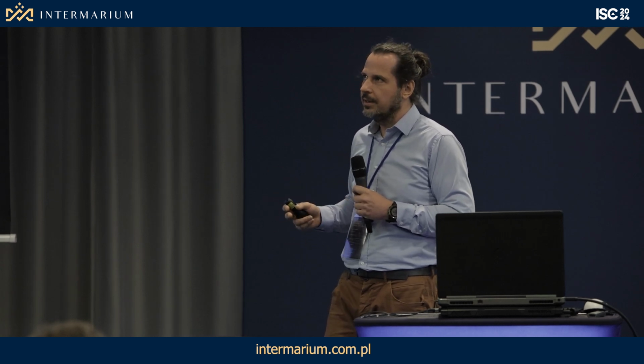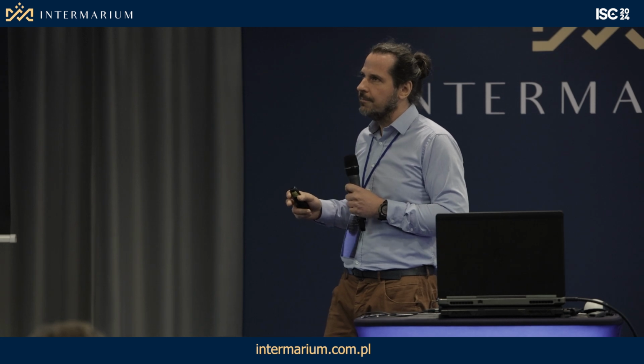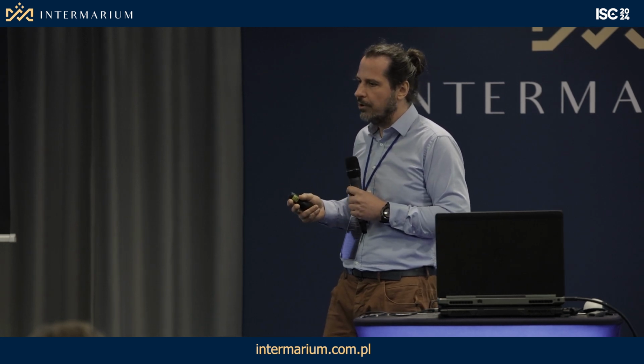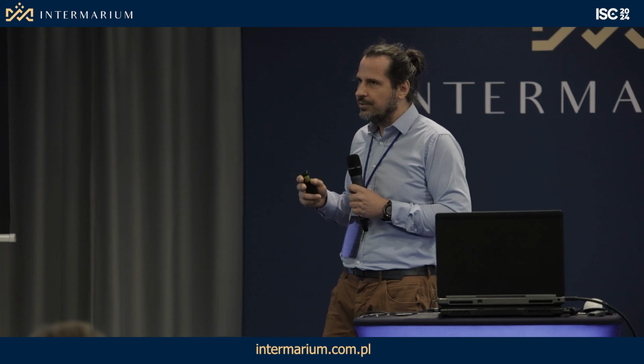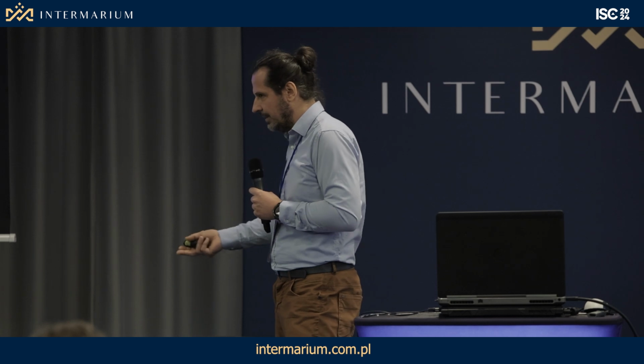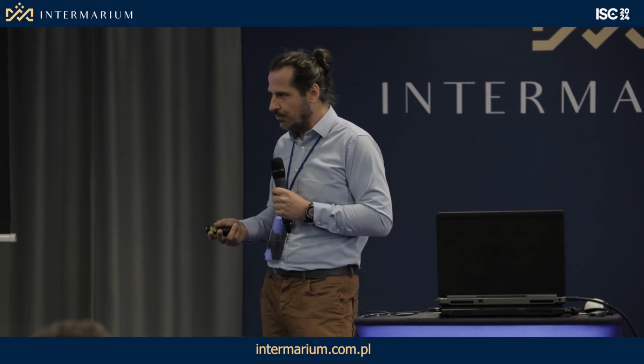Well, distances we always take into account during the analysis of a project with mobile robots. But fortunately, a larger distance is better for a mobile robot than a close distance. Why is that? Because grabbing the pallet and putting it down takes some constant time, maybe 35 seconds, always.